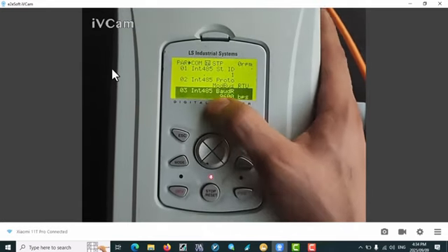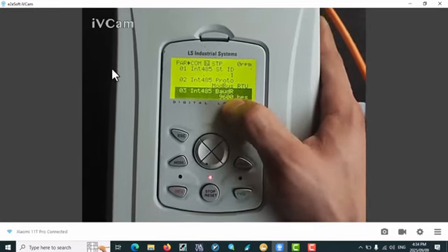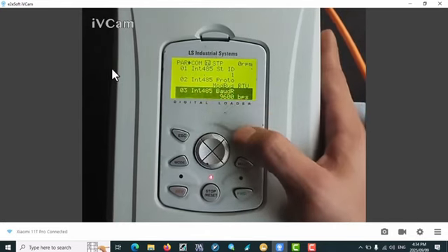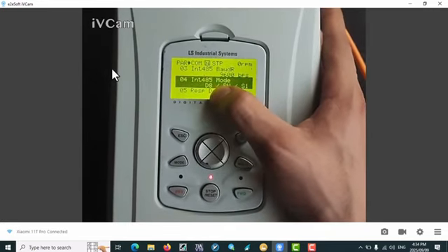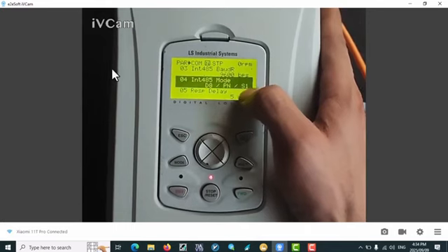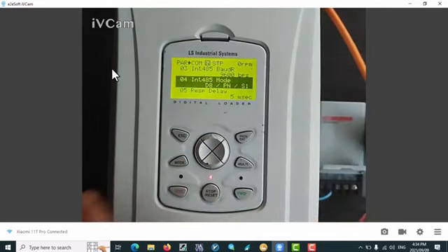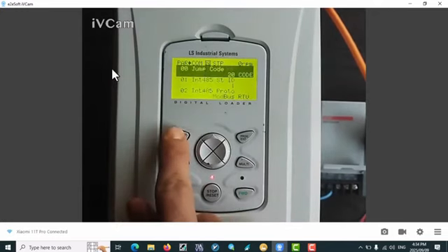But our baud rate in the settings related to the PLC, in the software, what was it? It was set to 9600. So in the COM settings, we also set our baud rate to 9600, but our next parameter is the number of data bits and stop bits, which here is 8-1, and in our PLC we've also set it to 8-1. So we've done the network related settings in the COM parameter group.